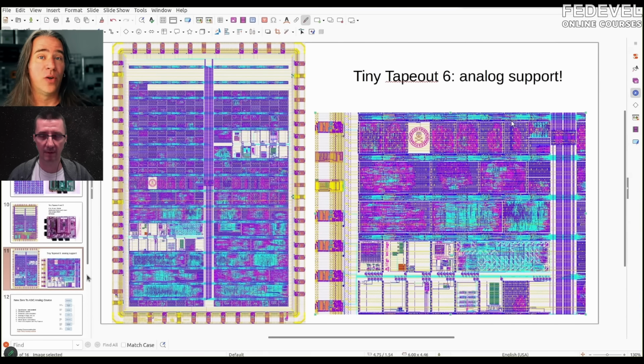Now in the analog world, you also have the equivalent of standard cells. Say I want an NFET, so an N-channel MOSFET. Well, it's got parameters basically. You tell it, okay, I want this NFET, the low voltage threshold NFET for 1V8, and give it to me with this length and this width and this number of fingers or whatever, and whoop, you just create it, and it generates that. Magic will generate it based on the rules and stuff that's inside of it, based on the PDK, and then you have this MOSFET.